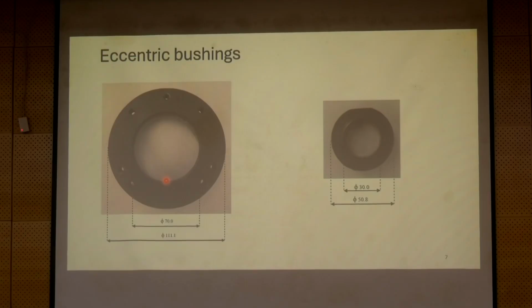If you consider the original point as C1, then when you place the bearing inside this bushing and connect the shaft, the center will no longer be at C1, it will be displaced by a fixed distance. These are polymer bushings, hard rubber, I would say, to place the bearing.